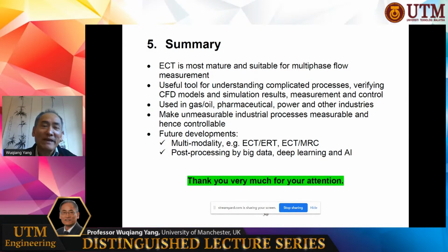My summary: ECT is the most mature compared with other industrial tomography modalities. It is suitable for multi-phase flow measurements. It is a useful tool for understanding complicated processes in industry, and verifying CFD models and simulations. I can talk a little bit more about this. Many people do simulation. They have CFD models. Now, how can you verify simulation results?